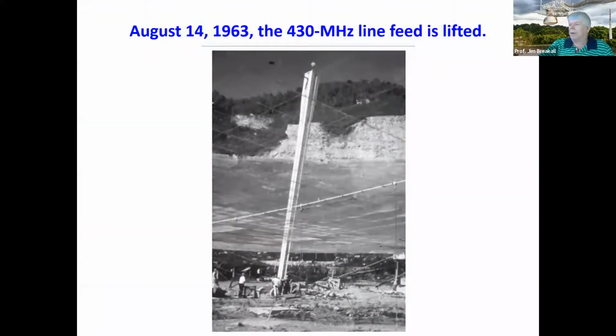Okay, here's one of the first antennas. Remember I said it's not a single point where the focus is on the spherical dish, it's along a line. And so what this is, is what's known as a waveguide again. It's sort of like a hollow pipe, and radio waves can travel in this pipe with very little attenuation. But then there are little slots along here, little holes that will leak out energy.